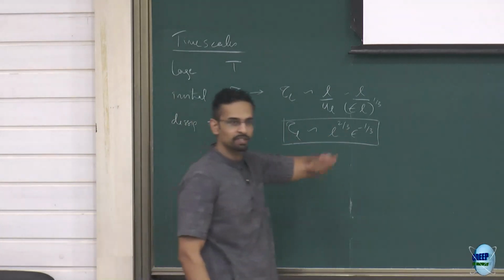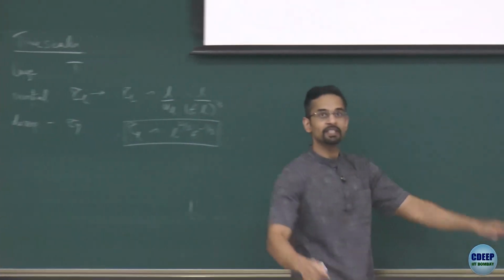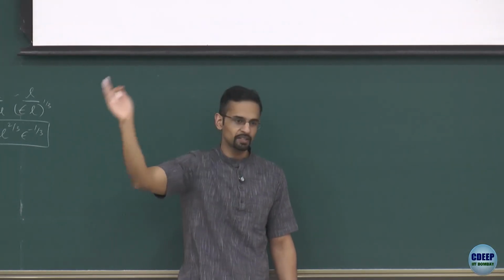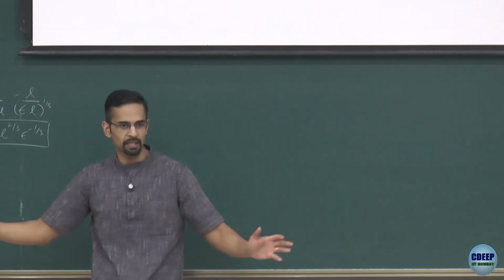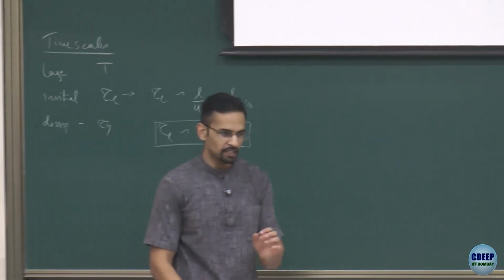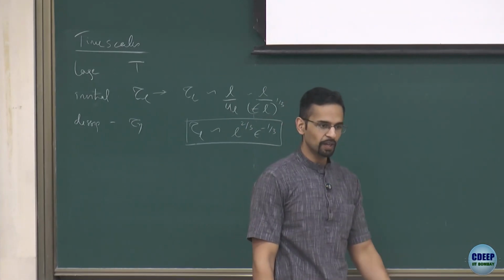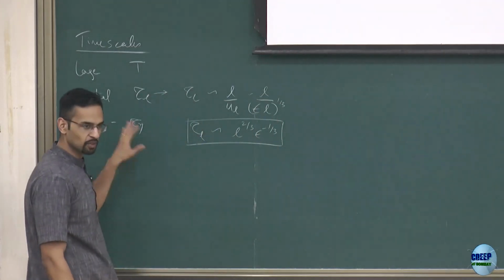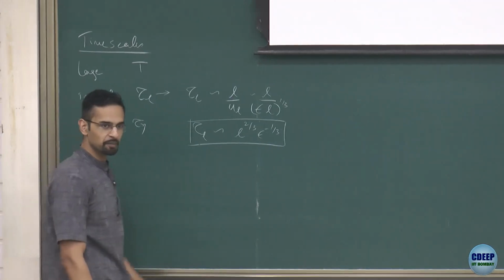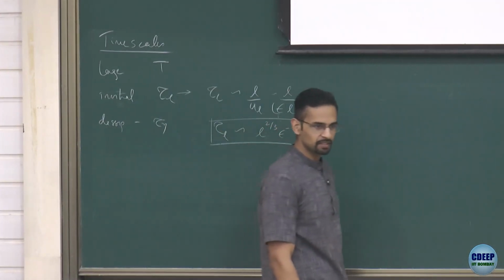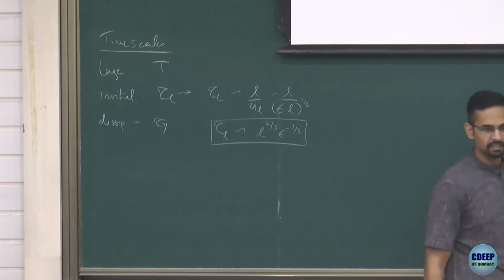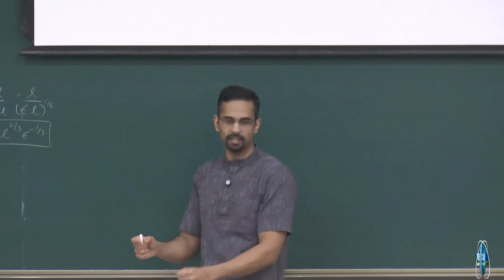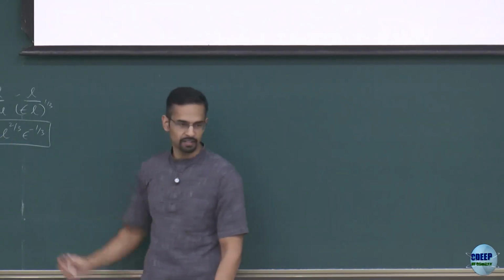Right? The large scales, you have this capital T, they control the big. So for example, if there's a fan in this room, the time it takes for the fan to turn round is setting the time scale of the big eddies. At the smaller scale, you have the Kolmogorov length and the Kolmogorov velocity, that basically sets the Kolmogorov time scale. So the Kolmogorov time scale will control the dynamics below the dissipation scale. Right? It's the intermediate range that you have a whole range of time scales for the different eddies that are there in your cascade. And those vary with L.